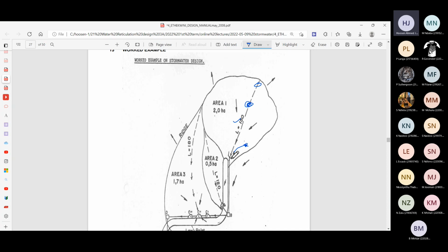Right. So what arrived at A would be gone down the pipe and gone. And the one that's from this furthest point is nowhere near point A. It would arrive much later, 15 minutes later, when it would flow down the pipe. So if you want the largest flow in the pipe, you want runoff from all regions in your catchment area to be reaching point A.